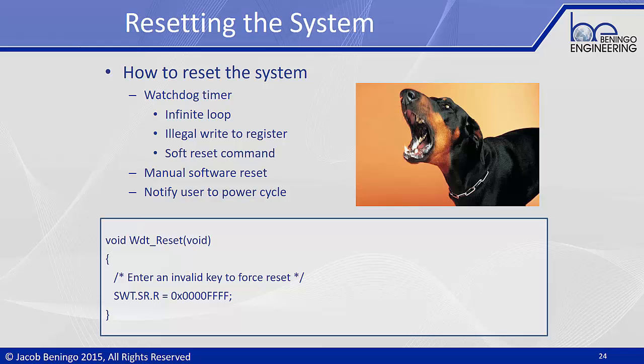Now, one of the questions that often comes up at this point is, how do I reset my microcontroller? As it turns out, there are a number of different ways that we can reset the microcontroller after we've updated the firmware, or when we're trying to go from our application to our bootloader. The watchdog timer is probably the most basic way to restart the system. And there are a number of ways that we can use the watchdog timer.